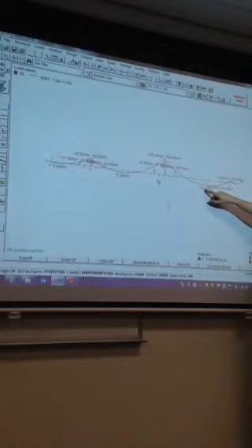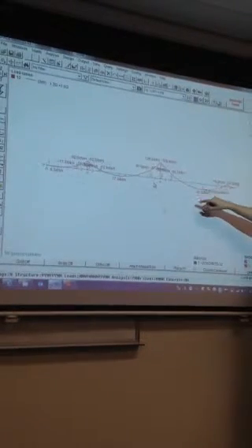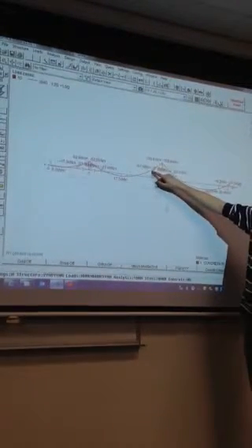So basically you've got three designs to do. So again, in this case, the worst case is going to be here, 45, the positive, but you've got the two negatives, those two points there, all right? And out of those two negatives, we choose the critical area of steel, so the maximum area of steel, and then we design with that.